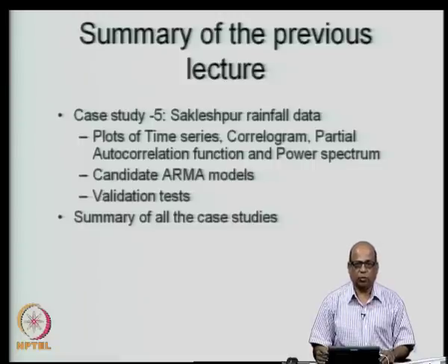The maximum likelihood values will choose a model which can be used for long term synthetic generation of data, whereas we use the minimum mean square error criteria for one time step ahead forecasting, and typically for flow forecasting we use such models.